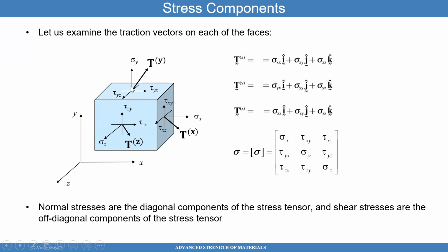I'll look at this traction vector, and what you find is that it can also be decomposed into the x, y, and z direction. The one decomposed in the y direction is called the sigma yy. And you can see here, sigma yy j hat, makes sense. J goes with y. You also have one that goes along the x direction, and that's stress yx. It's the y phase, makes sense. Y phase, the first subscript, and the x is the x direction. And you can see it has three components. I've covered two of them.